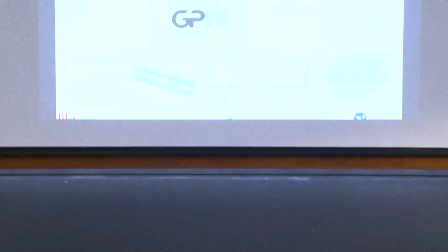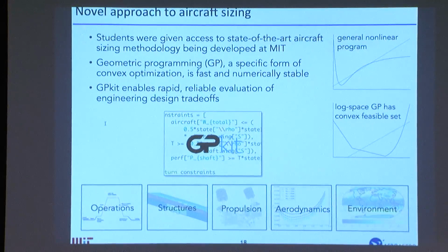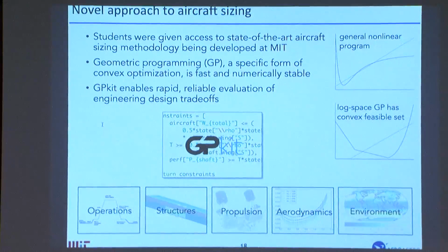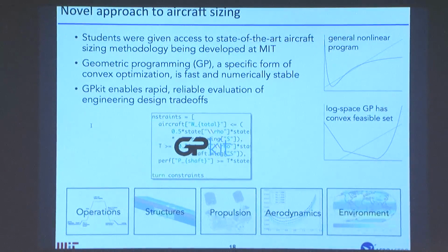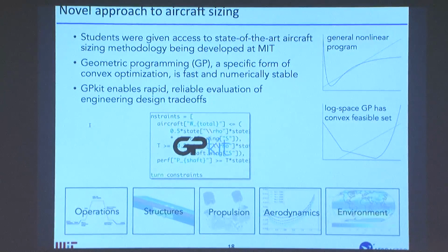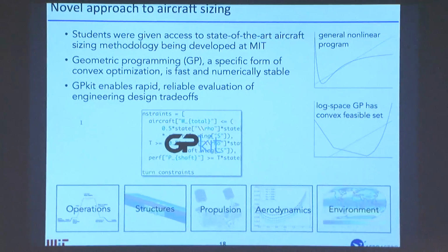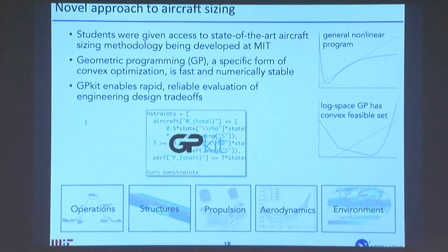And we used some sizing methods, Surtash mentioned them earlier, that were developed here at MIT to size the airplane. It turns out sizing an airplane, or figuring out how big it should be, like if I ask you, I want to carry 10 pounds for 5 days, how big should that airplane be? It's kind of a catch-22, it turns out. You'd say, well, the wing needs to be big enough to pick up the airplane. But then how big is the airplane? Well, it needs to carry enough fuel to fly for 5 days. Well, how much fuel does it need? Well, it depends how big the engine is, and the engine needs to be big enough to push the airplane that's big enough to carry all the fuel. It's kind of like catch-22.